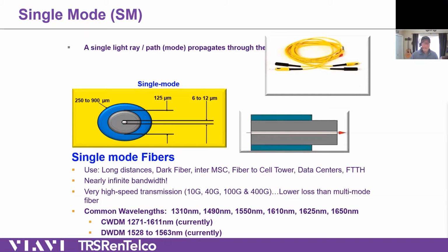In most cases, we don't use the word frequency anymore in fiber. So if you come from a wireless background and you're installing fiber now, you'll hear things like 700 megahertz, Wi-Fi, 2.5 gig, 5 gig, not 5G. When we talk light in a fiber, we tend to use the length of the wavelength. So 1310 nanometers, 1550, 1625. Those are frequencies, but they're terahertz frequencies. So 1550 nanometers would be something like 196.43 terahertz, which means nothing to most of us on the phone, unless you're working very well into some higher end applications than we're selling our smaller tools for.